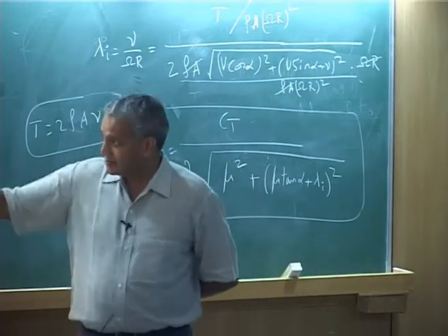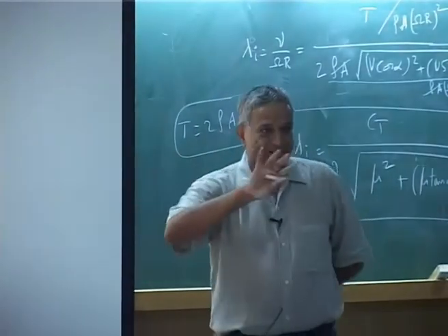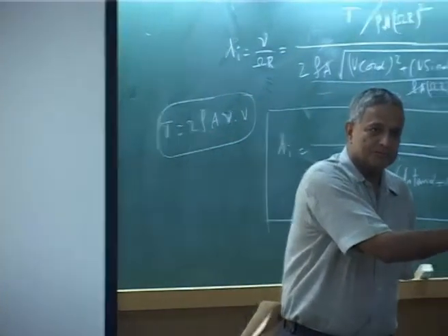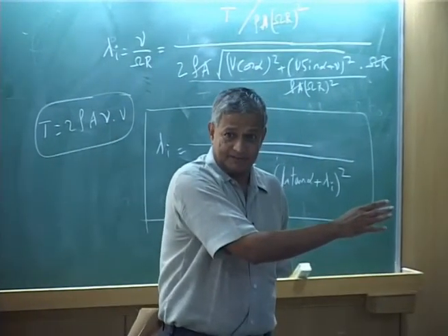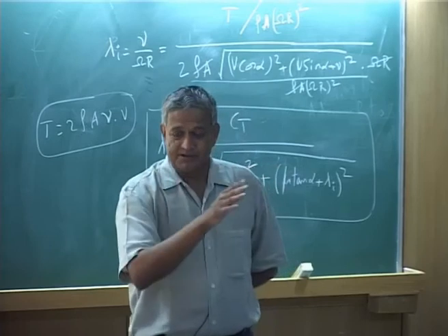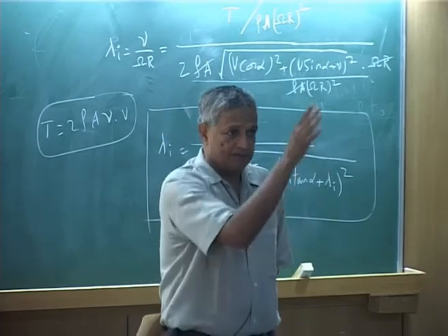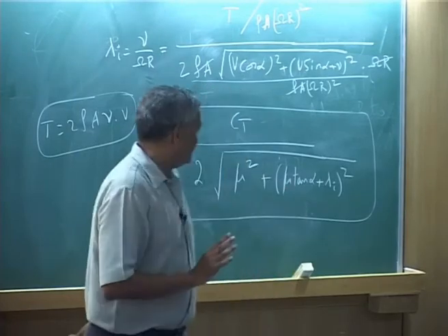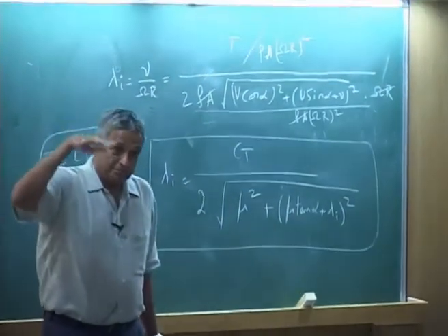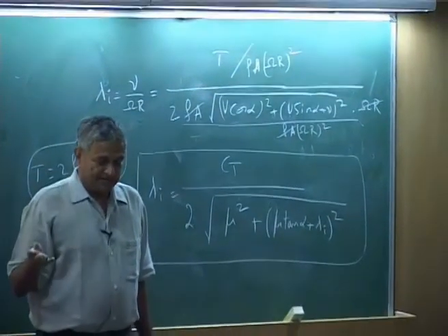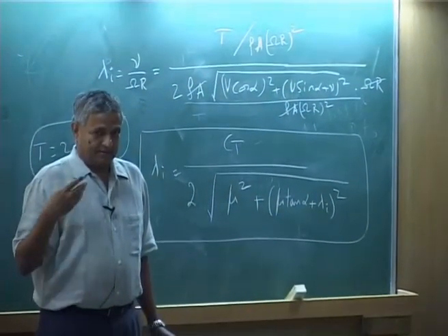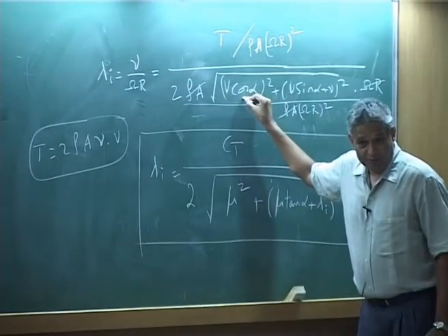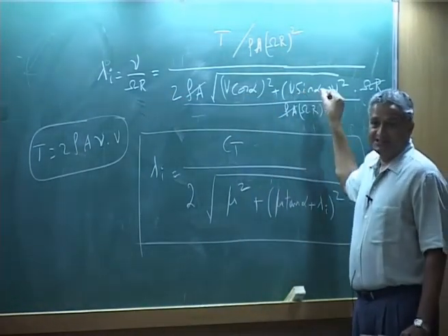That is why I am saying you relate the fixed wing on one hand, and the momentum theory for the rotary wing on the other hand, and then you simply bridge between hover condition and high speed flight. That is the reason in defining the mass flow rate you add V cosine alpha and V sin alpha.